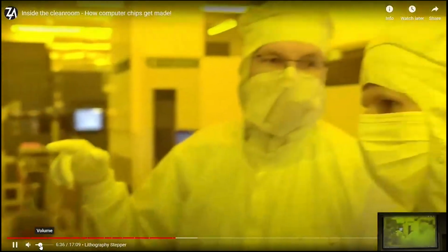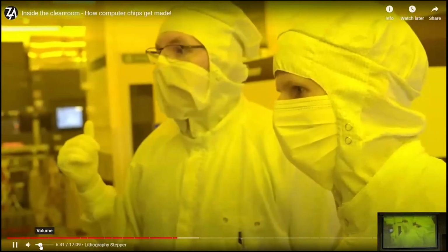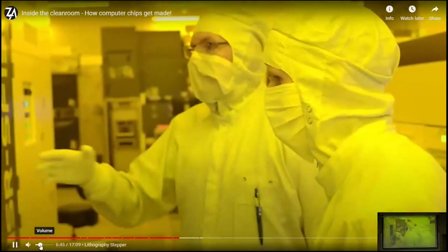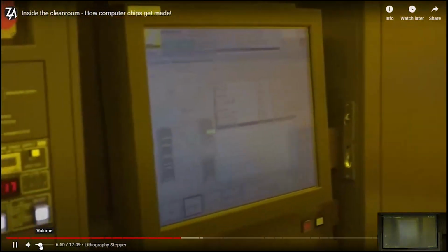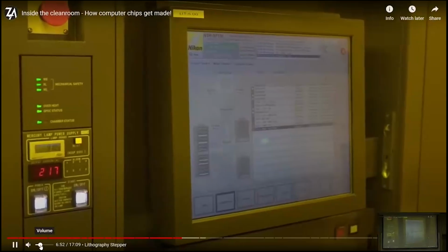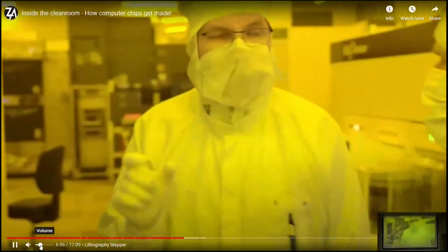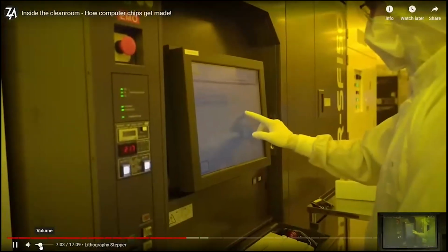This is the i-line stepper. We have an i-line stepper and a DUV stepper, with a 365 nanometer exposure wavelength, and this is 248. Okay. This uses a laser, this uses a mercury lamp. Yeah, this is for the more bulky, bigger structures, like top metal, the last few layers, where we have like 2 micron wide metal layers. And this is enough for that exposure.